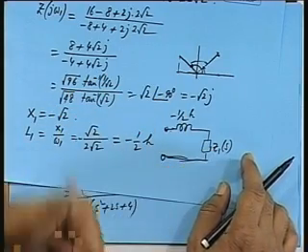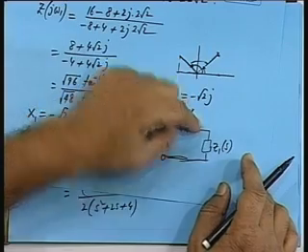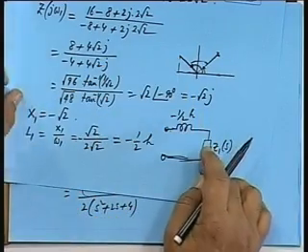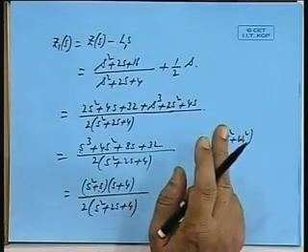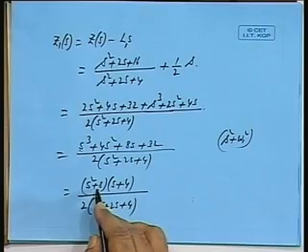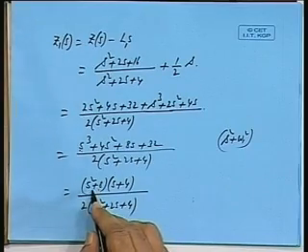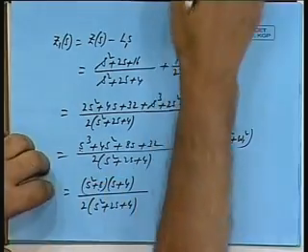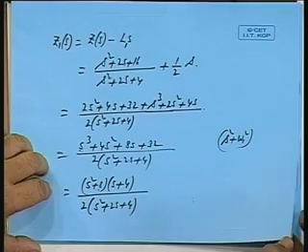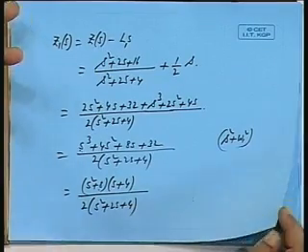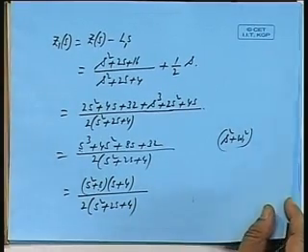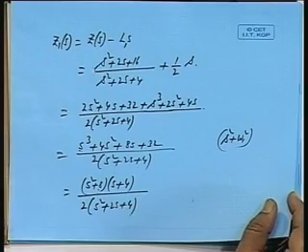So, what will be the impedance of this? It has to be 0, because this impedance is equal to this impedance. So, Z1(s) must have a 0 at that frequency. So, s squared plus 8 must be a numerator factor of this Z1(s). Otherwise, we could have a different factor also, obviously, we are making it equal to that inductor.